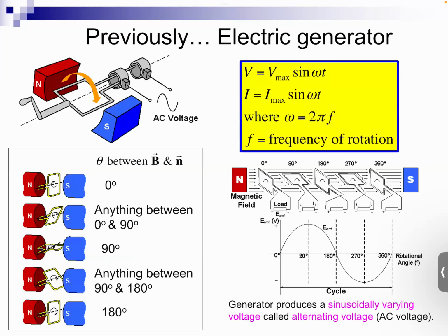And just a quick revision of what we've learned. We learned that if you have a coil and you rotate that in the magnetic field region, because you are changing the number of magnetic field lines crossing this coil by virtue of changing the angle or the orientation of the coil in the magnetic field region, you of course have magnetic fields between these magnetic poles going from the North Pole to the South Pole, then you are generating an induced voltage or induced EMF.